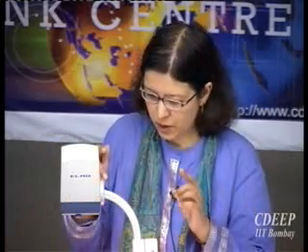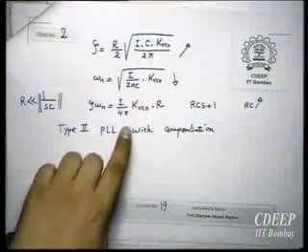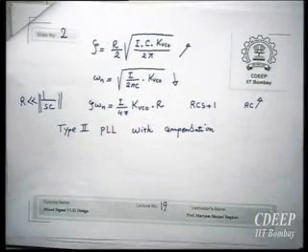Even if you don't use a current starved inverter and use something else, anyway you need some controllable delay component. Anyway, it will be a function that will define for you what the KVCO should be. What I'm saying is that you shouldn't consider KVCO as only affecting zeta omega n, or only affecting frequency. When I design, I look at my loop for stability, jitter performance and loop bandwidth, and I look at my VCO as a frequency provider. Then I write my equations, and then I will see how I should play with these values to get the best of all.